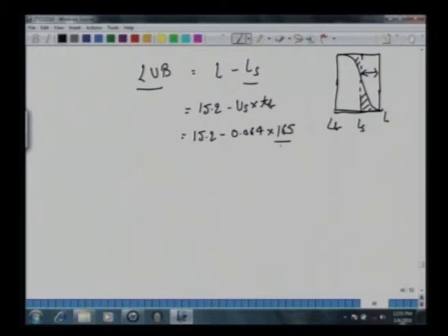We calculated from our breakthrough profile. We made some very small approximations. Data was given from 0 till 154 minutes, and at 166.7 we had this data of 0.018. So all you can do is draw a smooth curve through this to find out at what time it's just about to break. Okay, so that's your 165 minutes. So this number will be 4.66 centimeter.